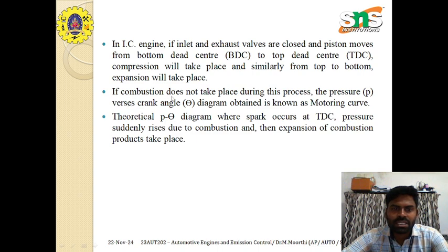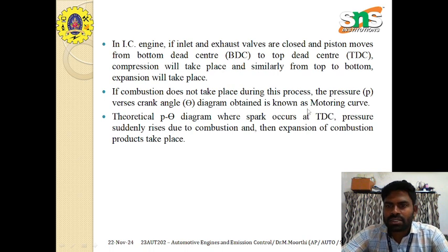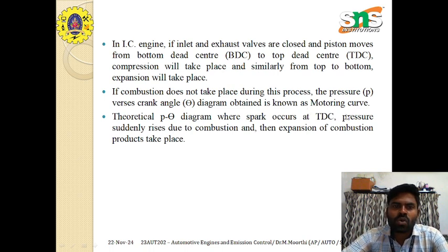If combustion does not take place during this process, the pressure versus crank angle diagram obtained is known as the motoring curve. If there is no combustion, it is called a motoring curve. After that, in the theoretical pressure theta diagram, a spark occurs at TDC, the pressure suddenly rises due to combustion, and then expansion of the combustion products takes place.